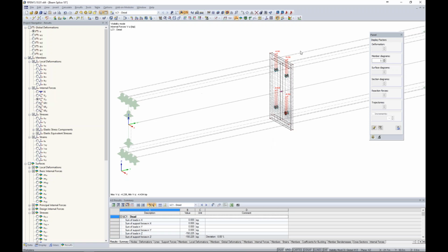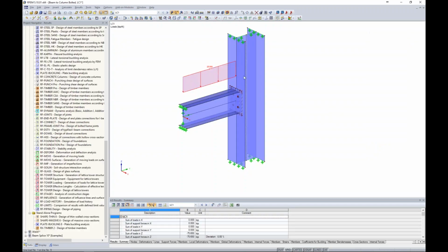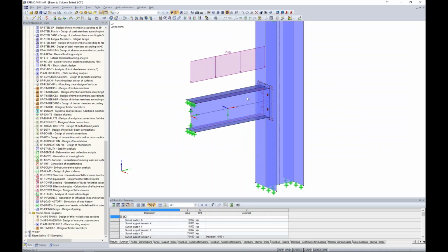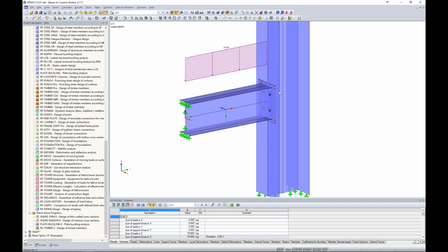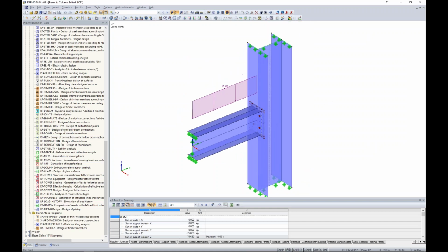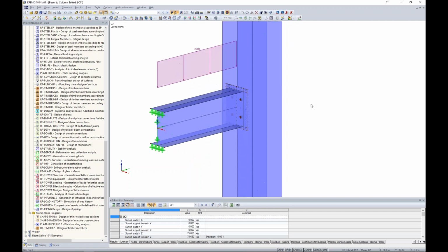Now, this was a completely symmetric design, which was very nice, but we all know that this typically is not the case. So what do we do when we don't have complete symmetry when we're looking at something like a contact solid? For this, I want to jump into my saved model here, and it's just a typical beam framing into a column. I went about it the same way of converting 1D member elements from my beam and my column. I even went about it the same way for my contact solid for my plate element, but there's something that's slightly different here.